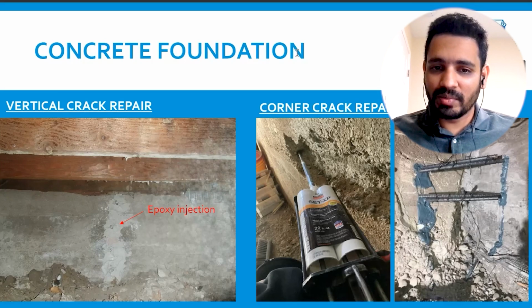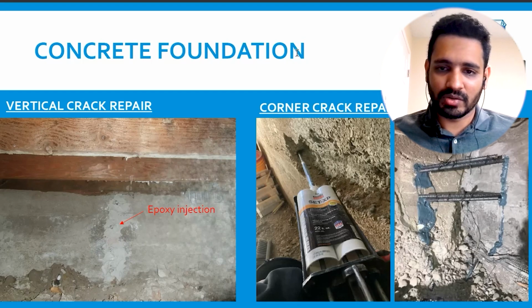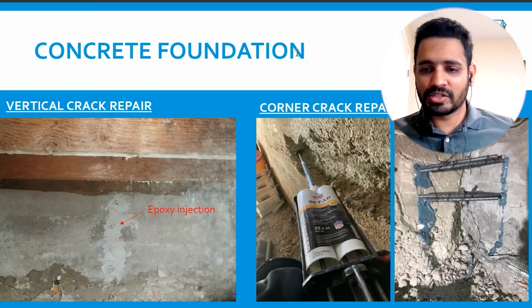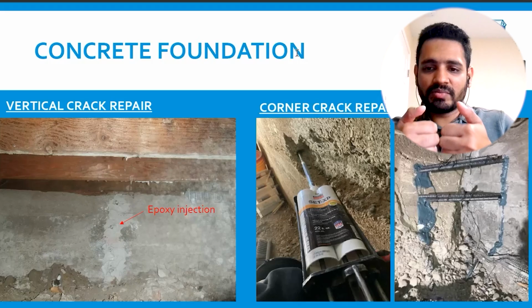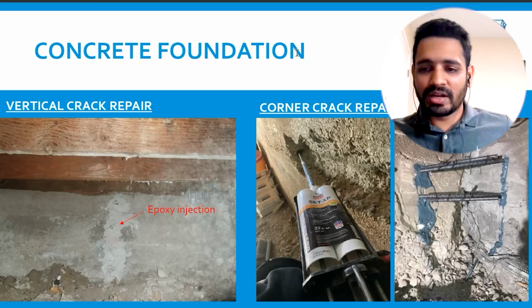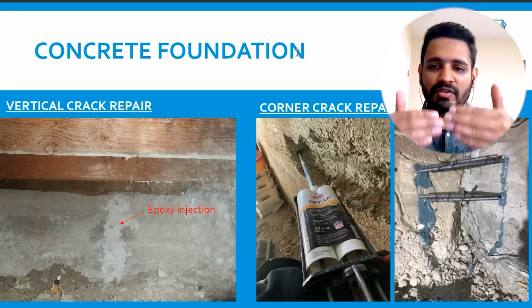It's a two-part component. There's a bonding agent that goes in, and then there's the actual epoxy that goes inside. That's your common application, and it's pretty simple, straightforward stuff. Prevents the water from seeping through back again, prevents the foundation from separating apart, or if you're on a hillside, you can also experience differential settlement.